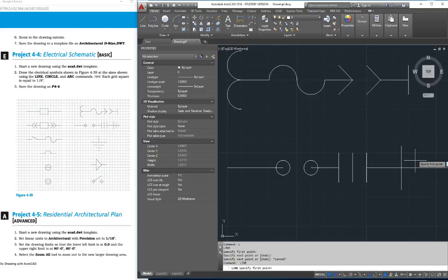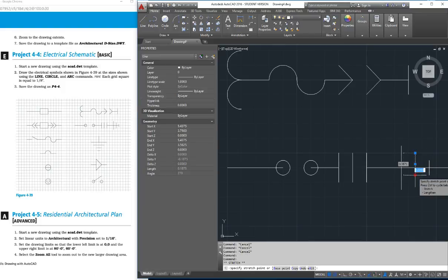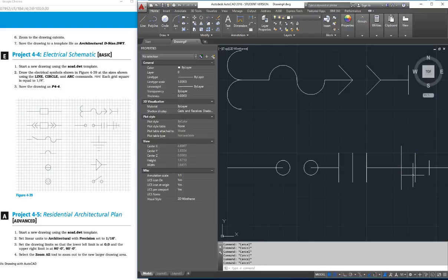And the next one is a little shorter. And the next one is a little shorter than that. Oh look, and this one is not long enough, so I'll click it and drag it longer. So that's going to let me then trim, enter. Now when I do this trim, what it does is it lets me shorten things, but you have to have something to shorten it to. So if I were to trim these out, I couldn't trim this one because it's a whole line segment. There's nothing to trim it to. So if I start on the right and go click, click, click, they're all gone.